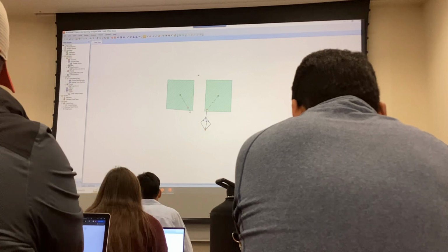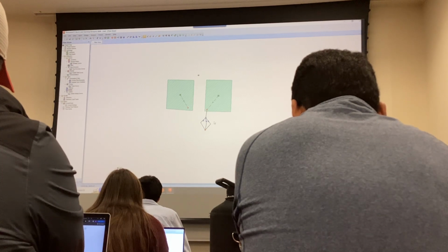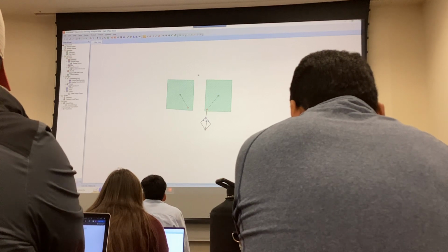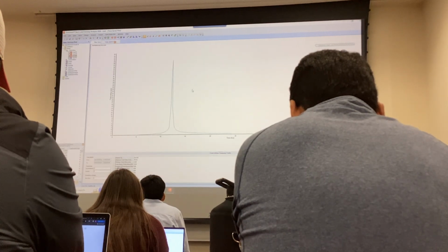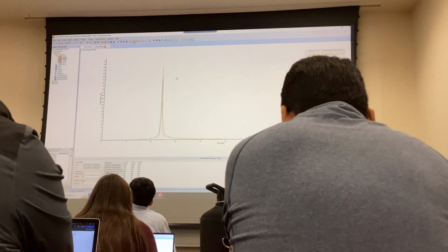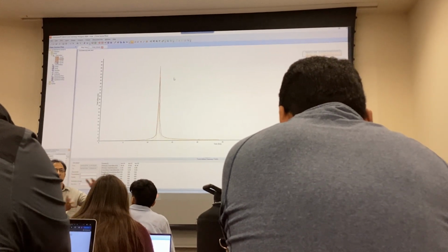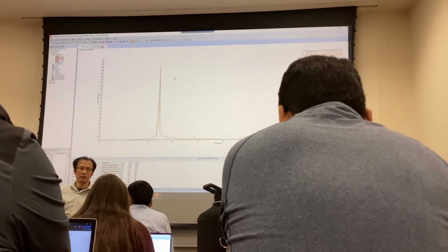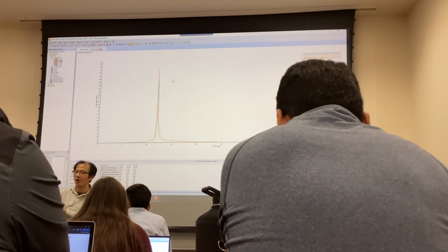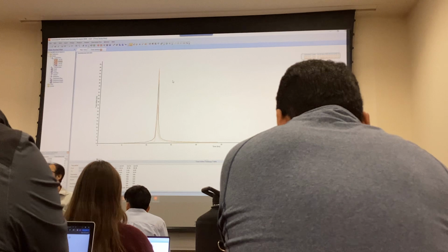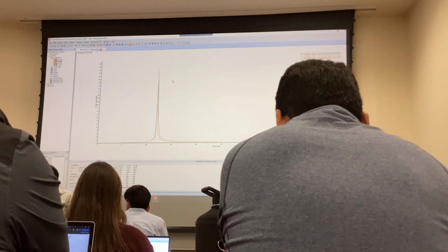For the junctions, because I don't care about each individual orifice, I want to know what the collective effect is. So I'm going to be plotting my outflow for my junction. Ah, there we go. So if you click on this, right, you can actually list out the pre-development flow. You have post-development, and then you have post after you install your detention basin. Now, what you want to see really is that your post after you install your detention basin doesn't exceed your pre-development. That's the main goal. Okay. So you can output